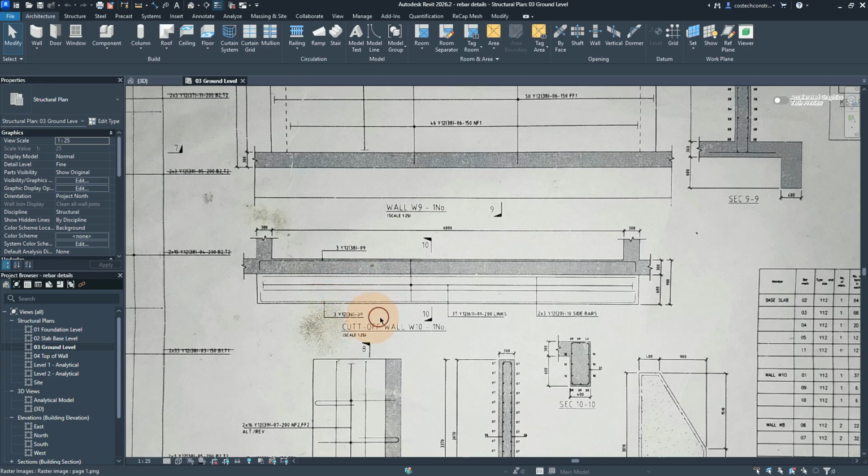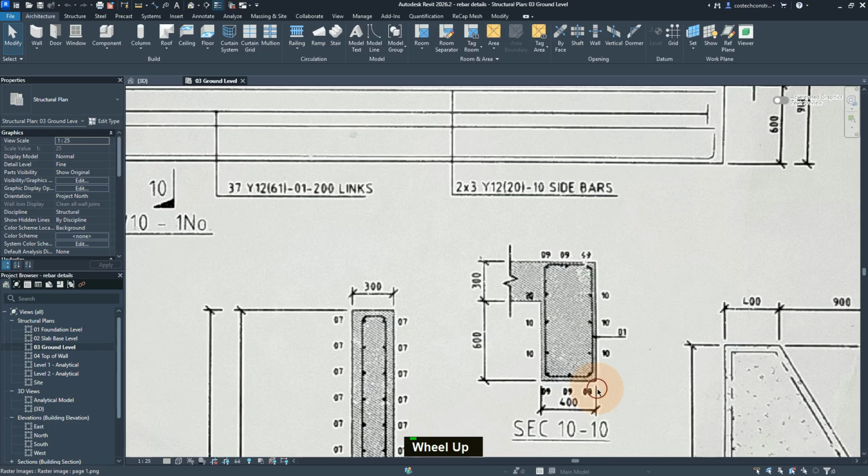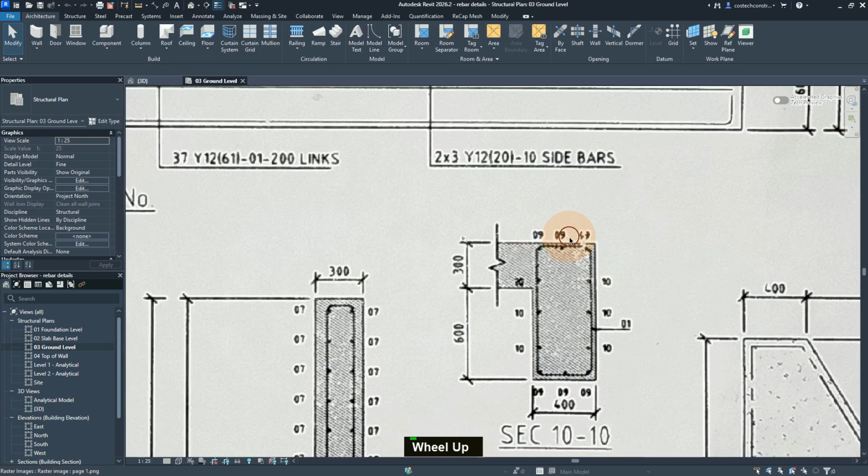So we can start to place our reinforcement. And this is how it will look at the section. So we'll have 3. For the top, we'll have 3 as the quantity. And you notice that the bar mark is 09. Then at the side, this will be one rebar set which has 3Y10, 10, 10. And then we'll have the bottom layer here and the other 3 provided at this side.